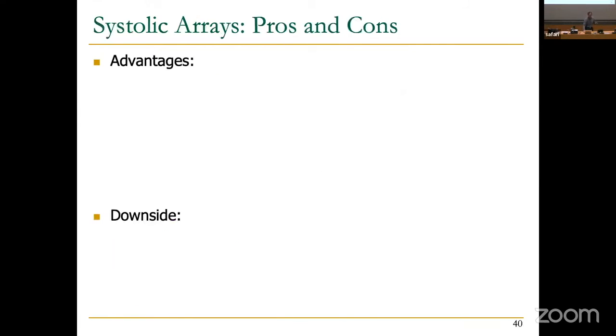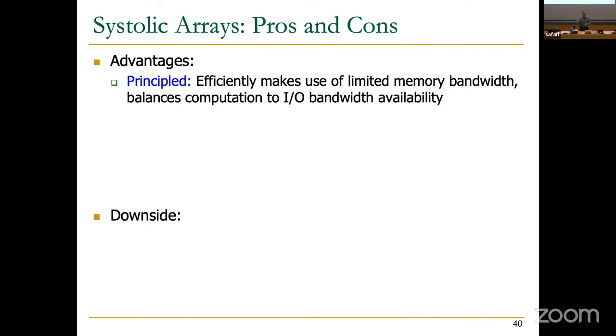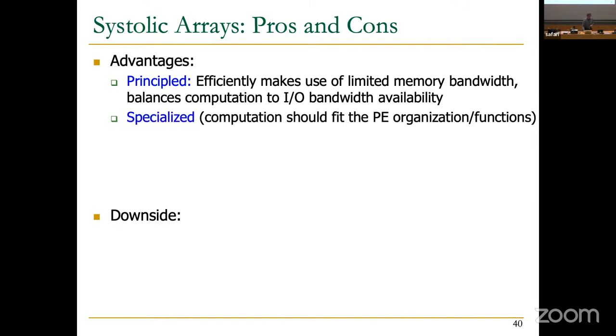So, okay, so I've given you the concept. The huge advantages are, this is a very principled design. It efficiently makes use of limited memory bandwidth, balances computation to I/O bandwidth availability. That's one of the biggest benefits of this. You basically chain lots of elements, orchestrate data flow so that you don't need to access memory, hopefully. You can implement systolic arrays on FPGAs also. FPGAs are a substrate to implement things as well, but that's a subject for something else.